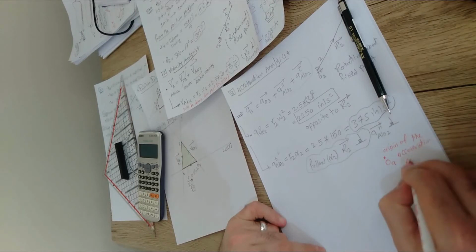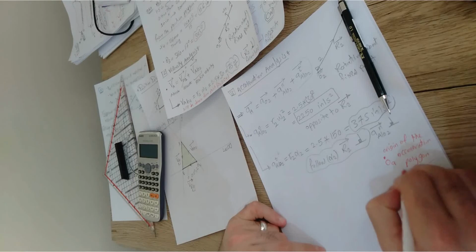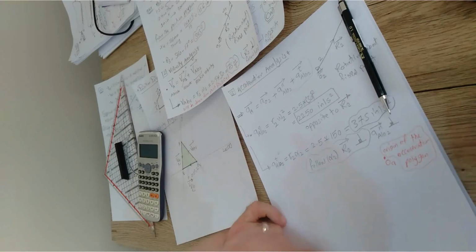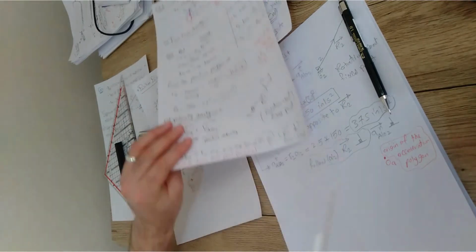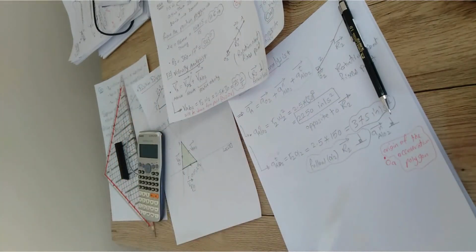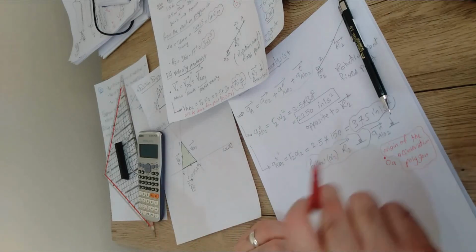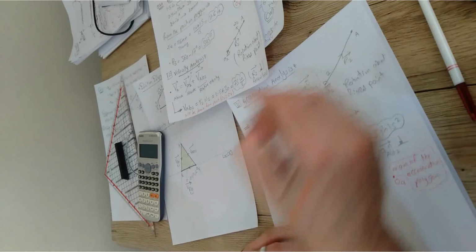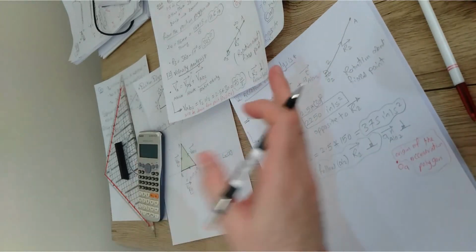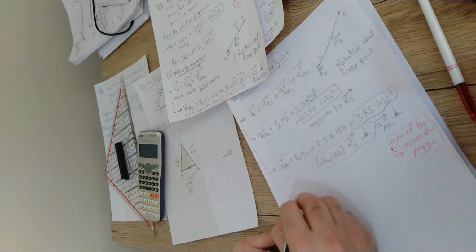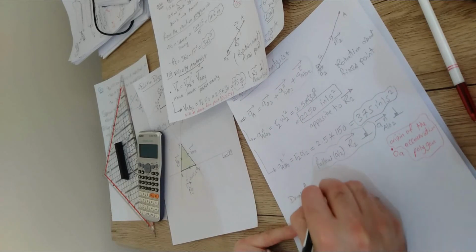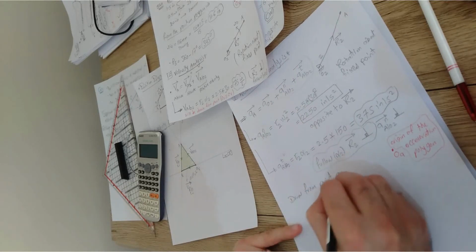So what does it mean? It means that any point that belongs to the mechanism with a 0 acceleration should be considered at this point, typically the same as the point OV that we defined for the velocity diagram. This is the origin point of the acceleration polygon or acceleration diagram, and any point with a 0 acceleration should be considered at this point, like point O2. So definitely point O2 will be known. In this case, we are going to draw from point O2, right?